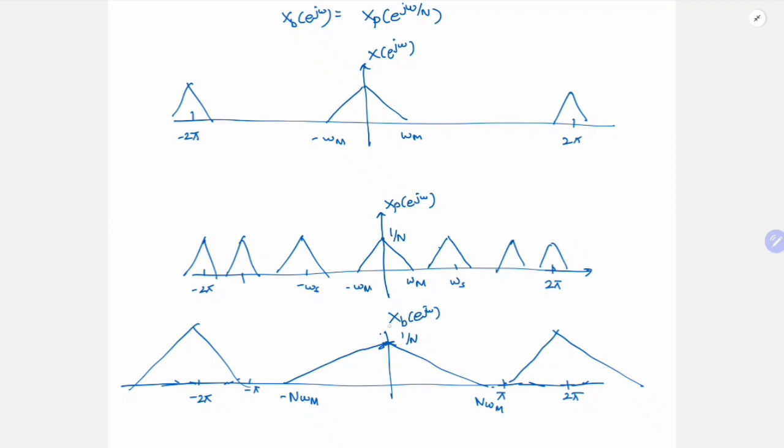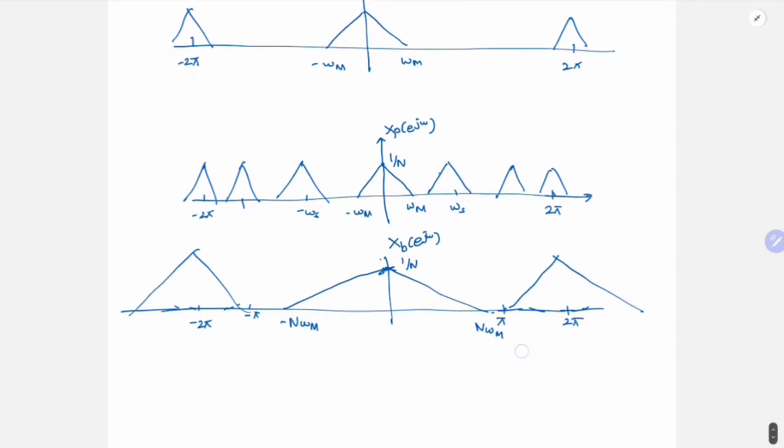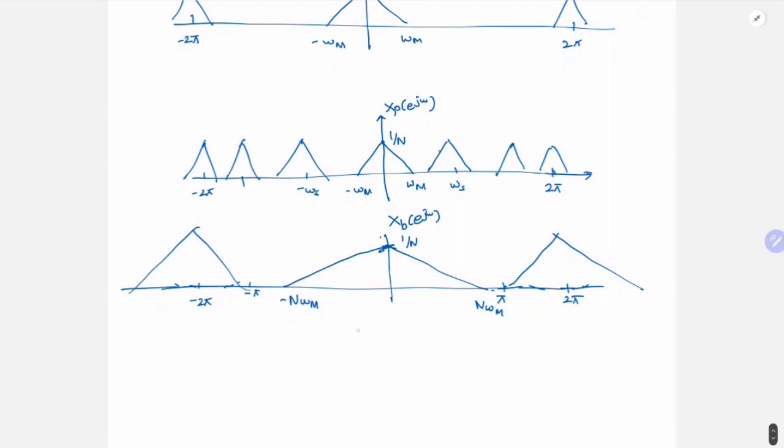So once we downsample it, we are getting back to our normal, close to Nyquist frequency, and we are getting only one of the replicas, or one of the X of e power j omega terms inside minus pi to pi, basically an interval of 2 pi. So this is called downsampling.